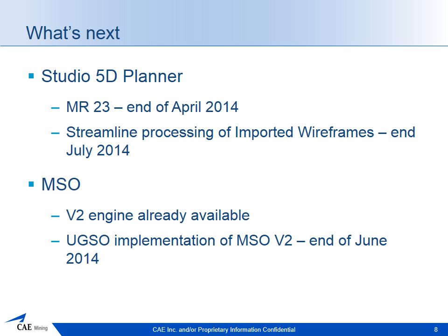But for the particular 5D Planner things that we're interested in, there have been some quite significant speed ups in the application of design definitions. So the process of applying the design definitions to your design strings is now much faster. We've got a new attribute type, which allows you to apply an attribute by using filters, and the filter construction is similar to the filters that we use in the interrogation setup. So you can use a design type, you can use a description from a design definition, or you can create your own custom filter, and that allows you to automatically apply design attributes to your activities.